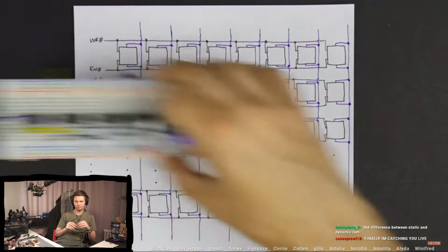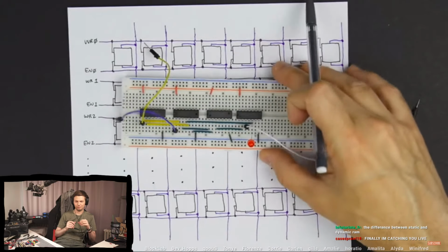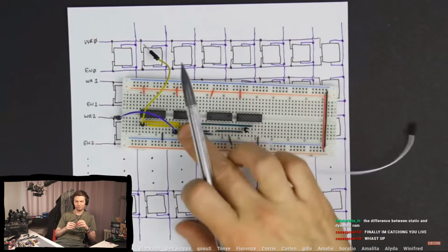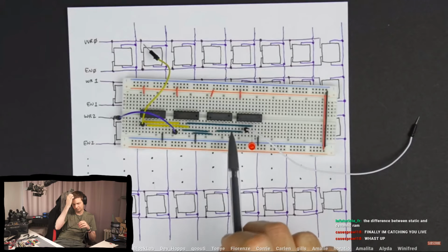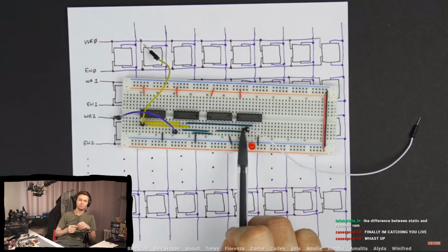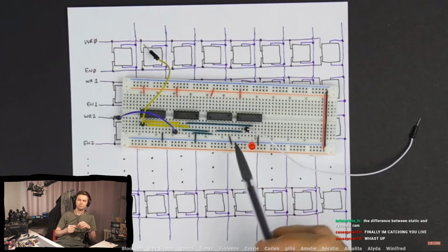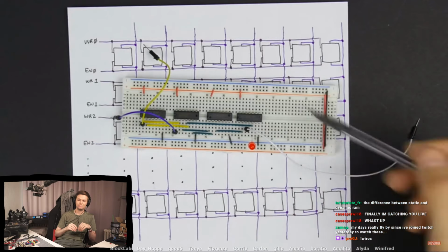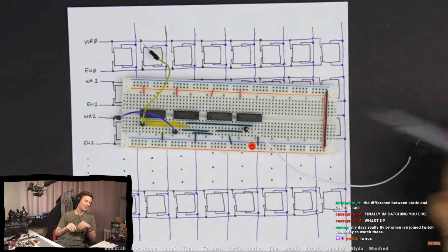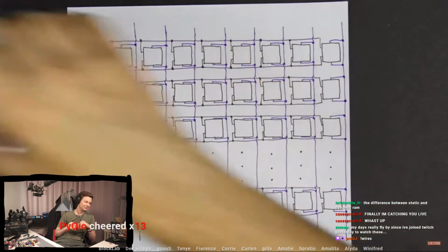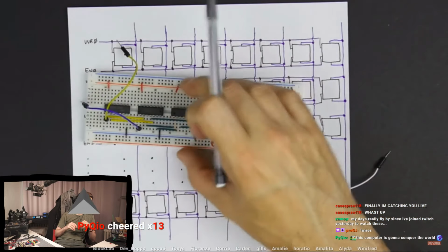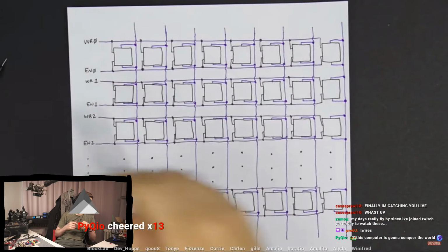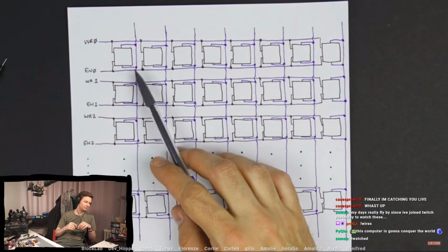Whereas if we used a flip-flop circuit or something like we've been building with our registers, as you know, once you store a bit of data in here, it stays there essentially forever until we take the power away. So as long as this is powered up, we don't have to constantly refresh this or anything. We store the data in there, it stays there. And so if we're using this type of memory cell, that's referred to as static RAM. And that's what we're going to do for our computer.